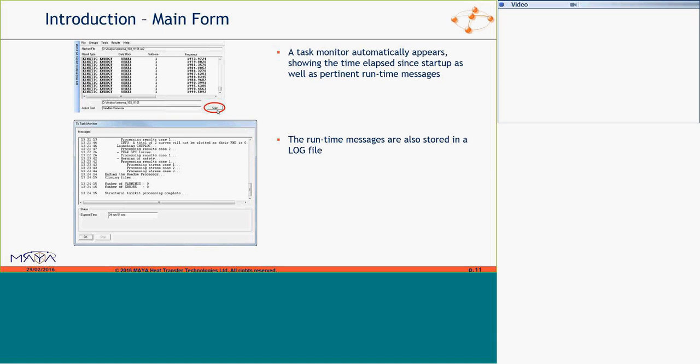The interface picks the processor and writes a definition file, and then tells the processor where to find the definition file. So it's kind of like NX. When you're using NX CAE and you want to do a Nastran solve, NX is going to write an input file, launch the Nastran executable, and tell Nastran where to find the Nastran input file. So this is a similar process here.